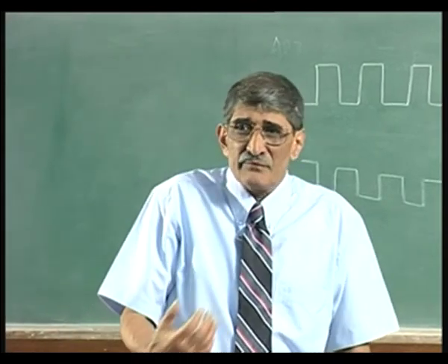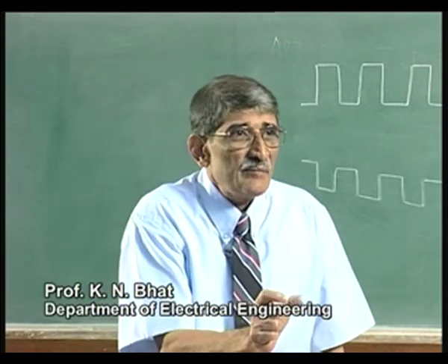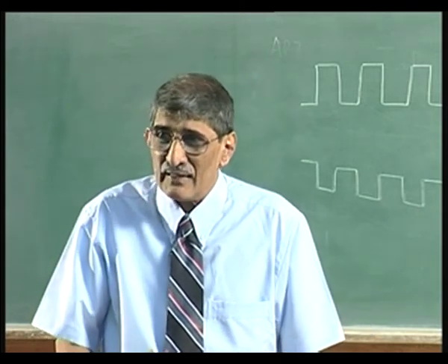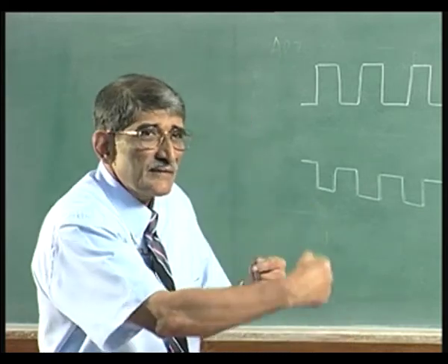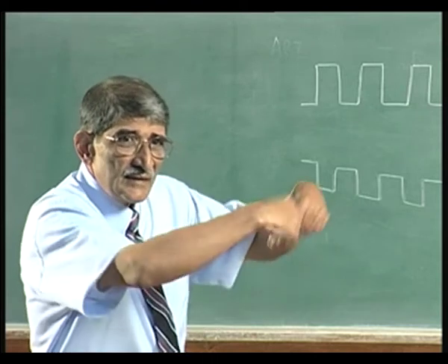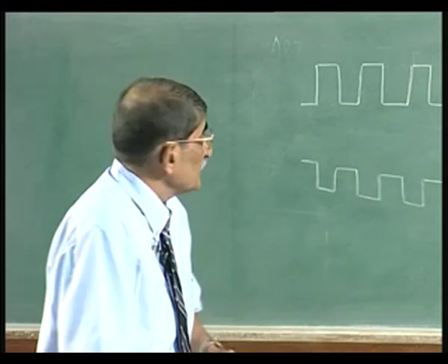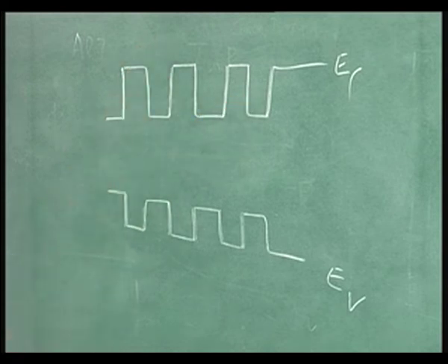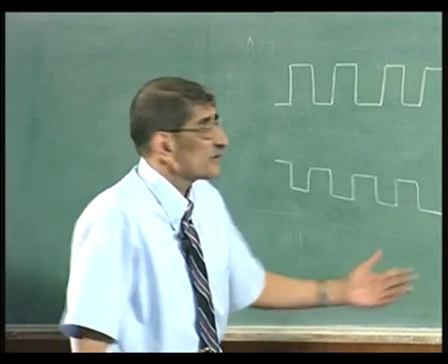It is just like, if you have atoms. I have seen no explanation in the literature saying why you call it superlattice, but it is very clear. If you have atoms nearby in the lattice, what is the potential variation? When you move from one atom to another atom, you have the potential variation. As you go near the atom, there is a dip in the potential. You have the potential variations going like that. In the case of a lattice, the spacing between lattice atoms is a few angstroms. Same way, if you keep these layers very thin, it is equivalent to the lattice atoms. That is why it is called a superlattice.